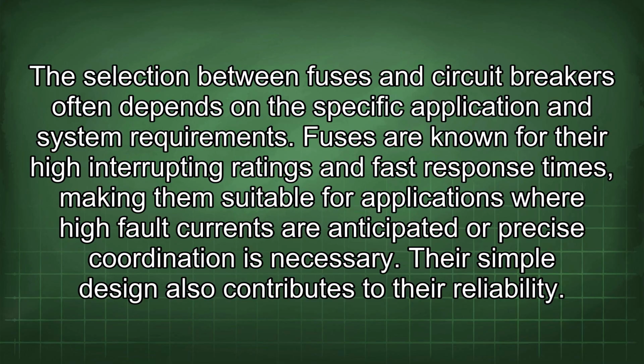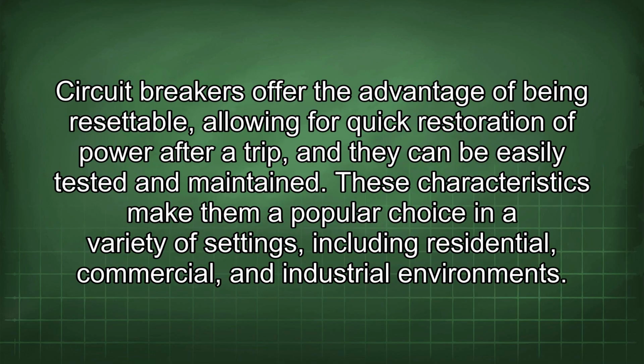Fuses are known for their high interrupting ratings and fast response times, making them suitable for applications where high fault currents are anticipated or precise coordination is necessary. Their simple design also contributes to their reliability. Circuit breakers offer the advantage of being resettable, allowing for quick restoration of power after a trip, and they can be easily tested and maintained. These characteristics make them a popular choice in a variety of settings, including residential, commercial, and industrial environments.